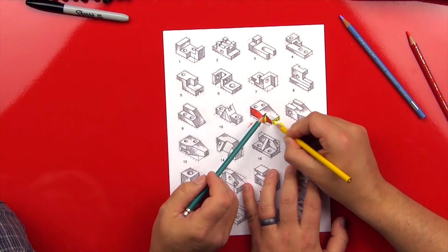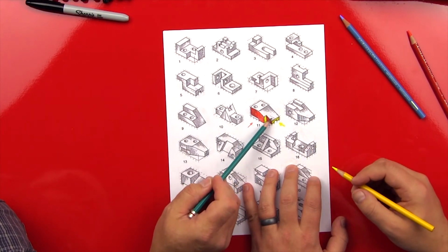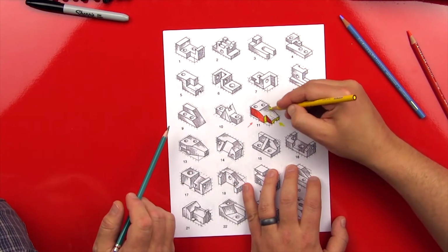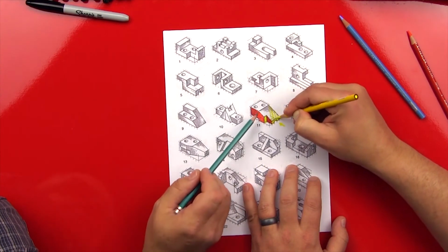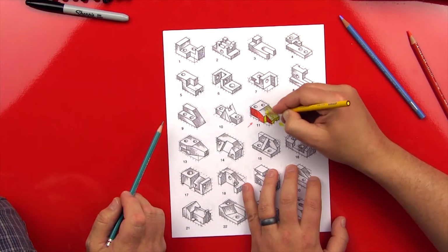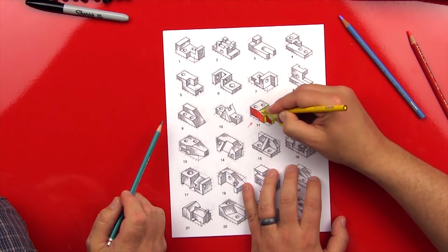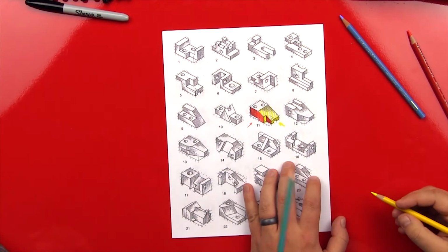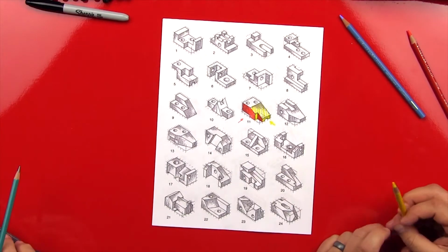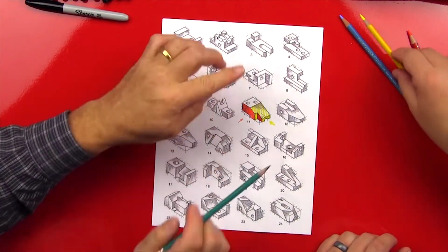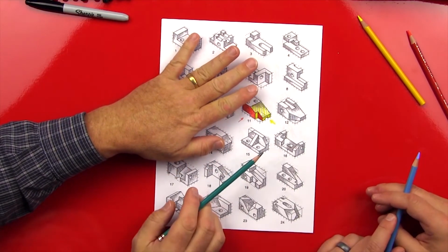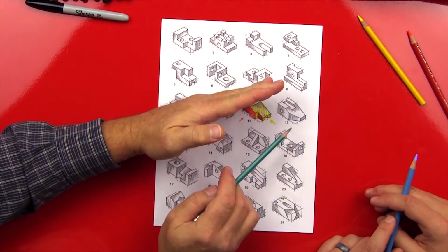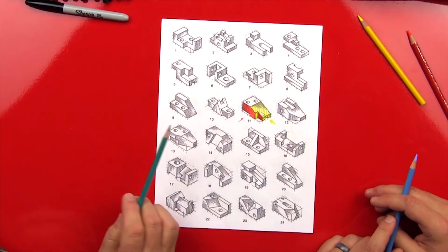Ooh. And I want you to basically crosshatch just with lines, a bunch of lines, that thing. Okay, and up here. I have a feeling I know why. Now that's exactly what you're going to see from the right side view. This plane, the one that we just kind of put lines across, ends up being foreshortened and projected out here to the right side view.